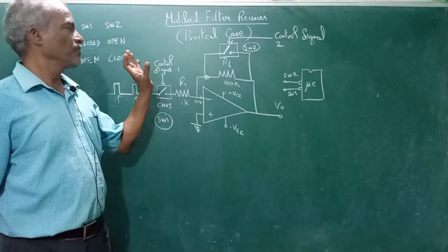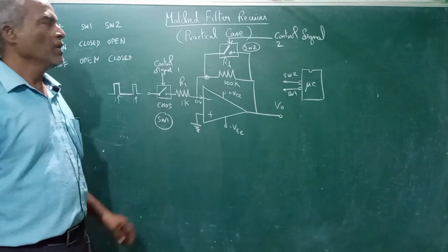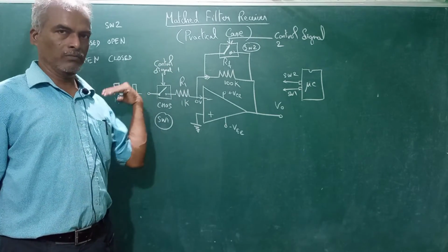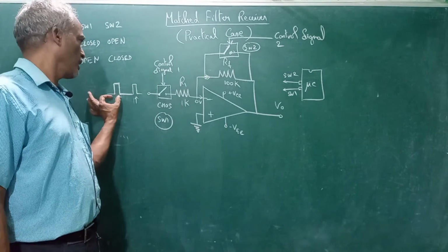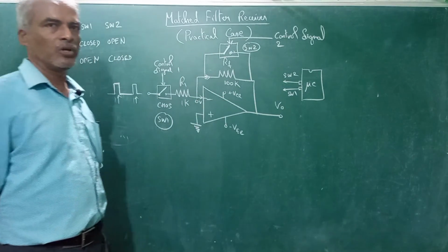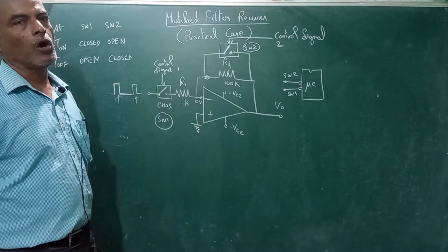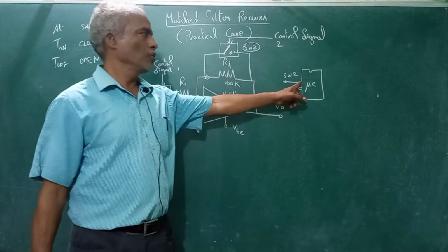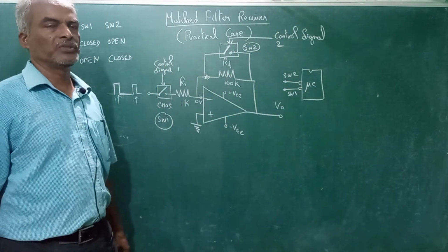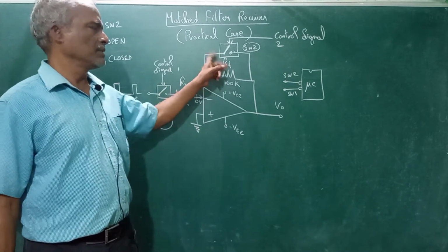For knowledge of the incoming signal, we have synchronous circuits that can synchronize the switching time. The circuit will synchronize exactly at the on time, and that information is sent to the microcontroller, which immediately knows at which point to go on and off at these 2 pins of a particular port. Thereby we can reduce the noise in the system.